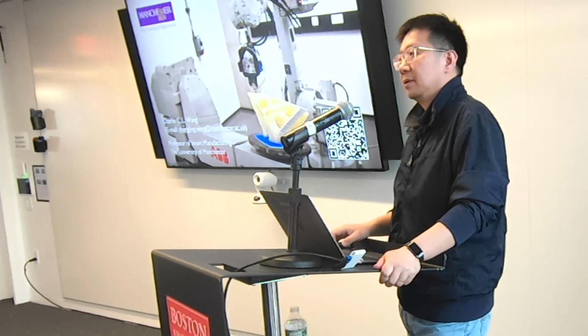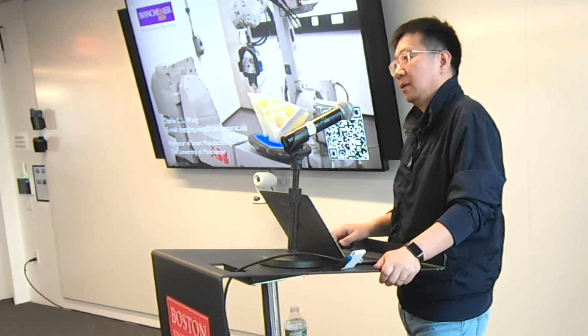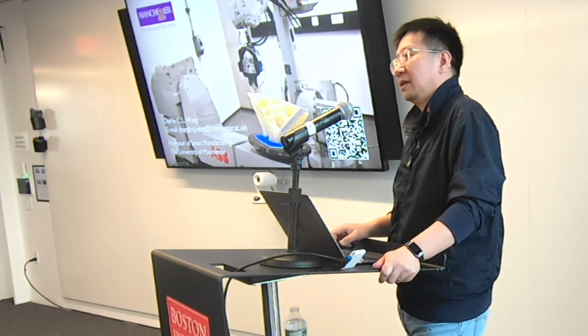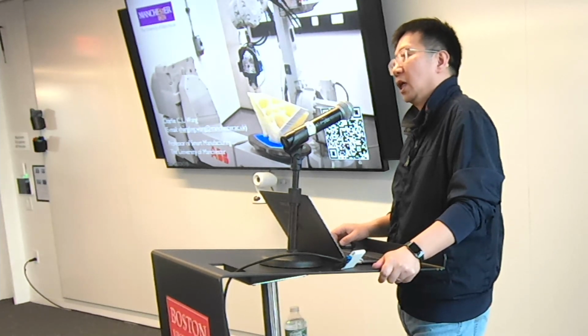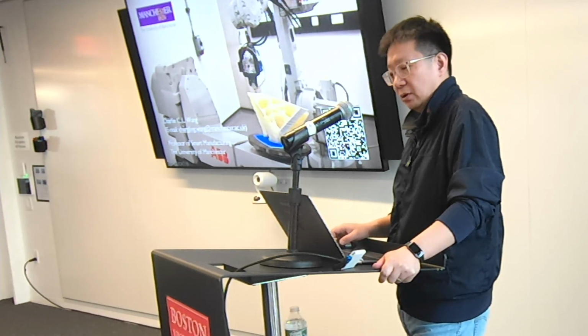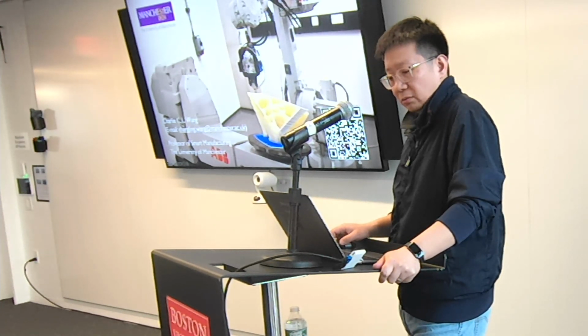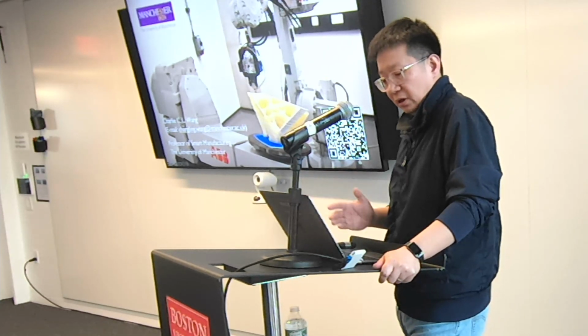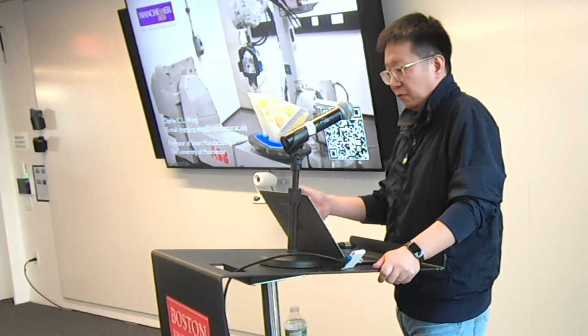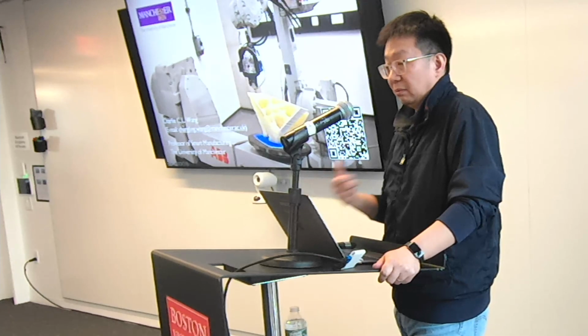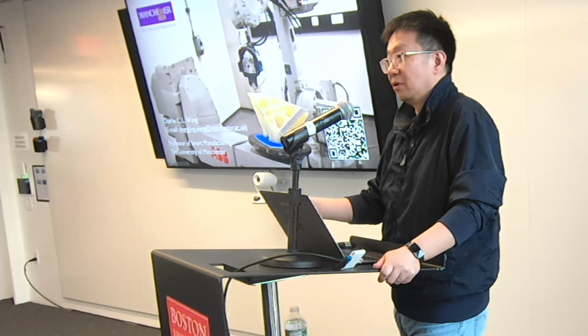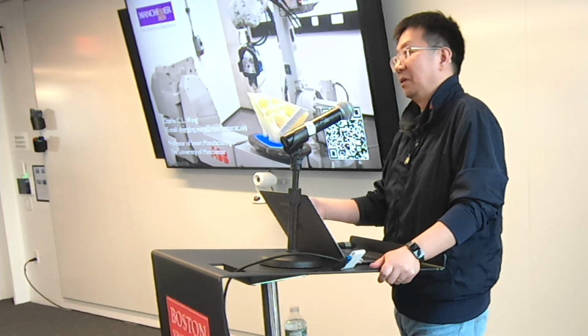Sorry, you mentioned that you're measuring the force as a mechanism of feedback. Which force? The compression force at the printer head. So the reaction force on the printer head? Yeah. Interesting. That's how we control it: when you feel the force is not big enough, the idea is we slow down the motion. So basically, in a local region, you have more material accumulated there. That makes a total difference to the printing quality.